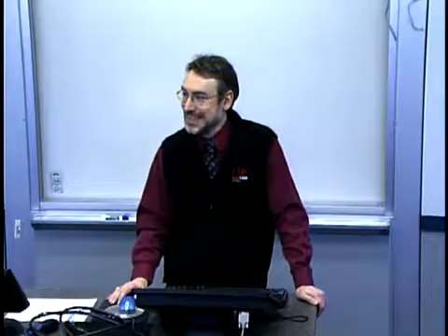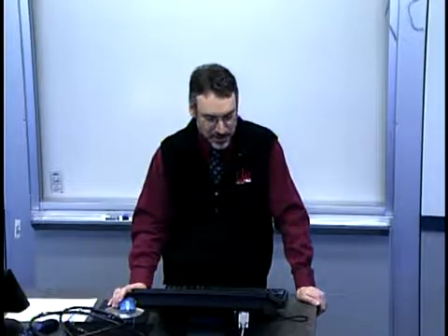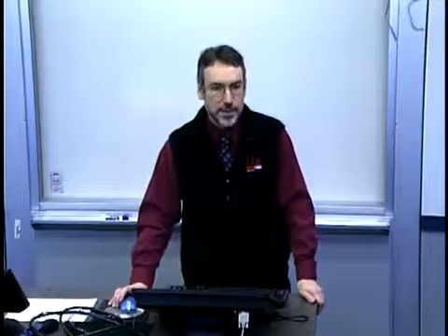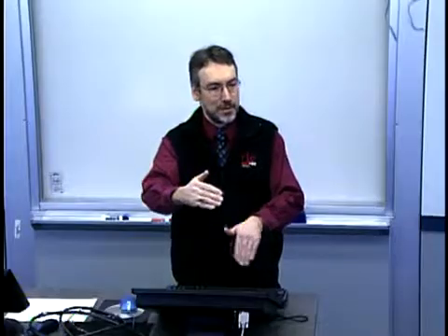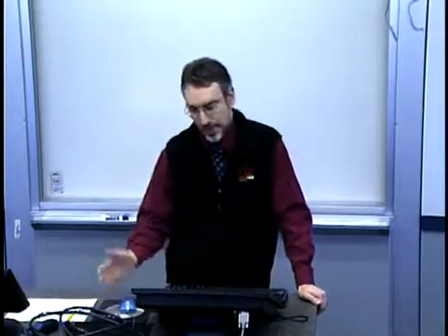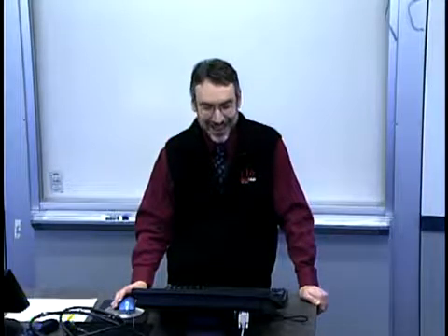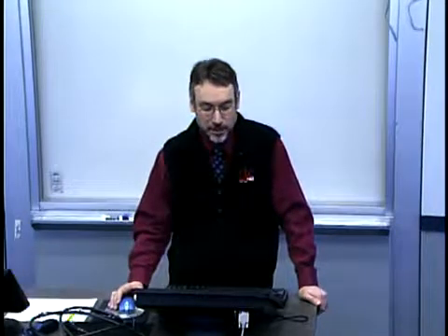Is it uniform? Not especially. Although you always have to be really careful looking, because on any kind of plot you want to really look at the spread. I mean, here it's kind of magnified because here's 0.7 inches and we're down to about 0.697 up to 0.702, say. So that's not full scale, right? But if we zoom in around whatever nominal is, and in fact it's not even clear what the target dimension was. I might guess that it was 0.7 inches because that's a nice round number, but who knows, right? So it's definitely not uniform.